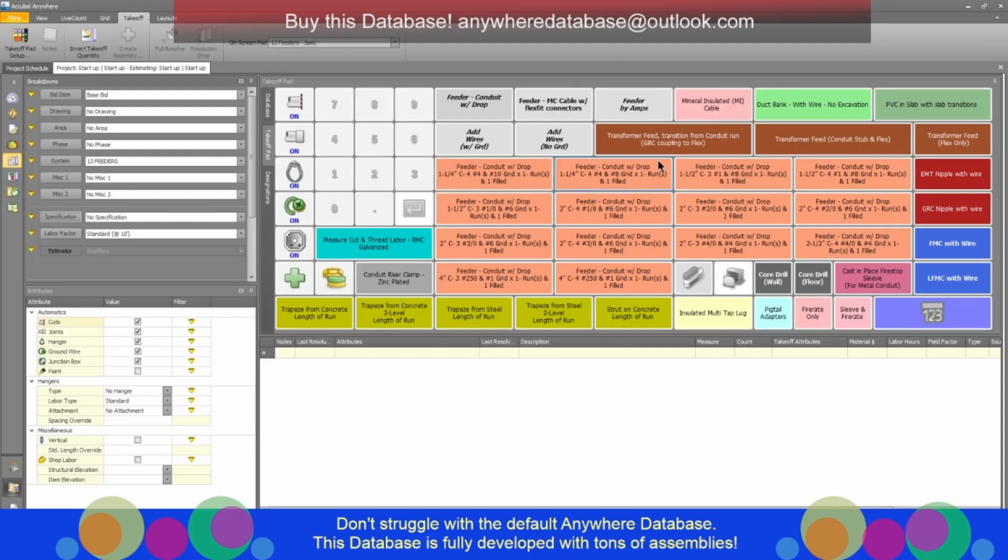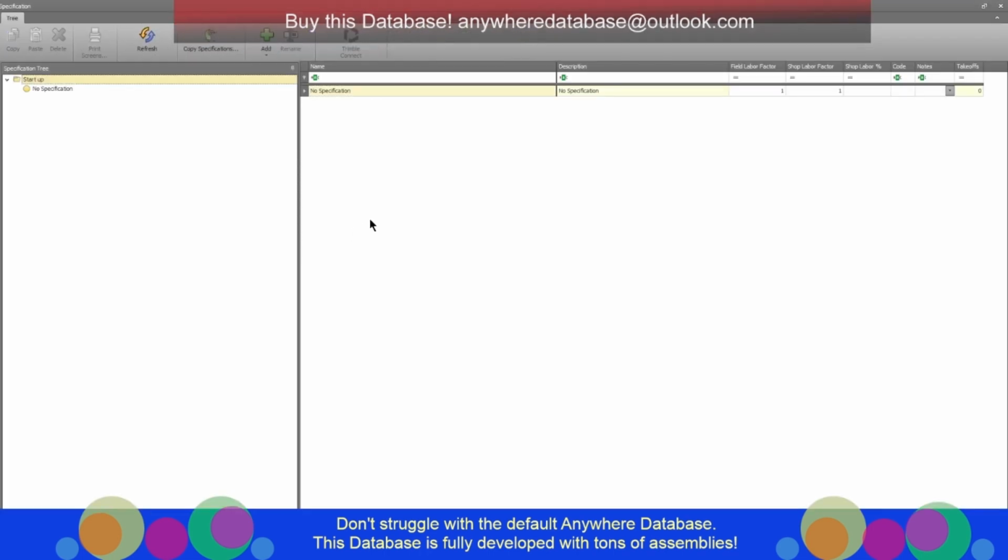I want to make sure I'm purposefully clicking and explaining. So I'm going to hit the specification button here to the left of no specification. So click that, brings up the window. And this is one of the Anywhere traps that I will say is a little weird: you would think when you're staring at this window that you would pick add specification, because you think, yes, that's what I want to do. I need to add one, but that's not what you want to do. Either these should be opposite, or this should be completely labeled differently. This really should say build custom specification, because that's really the path that it leads you down.